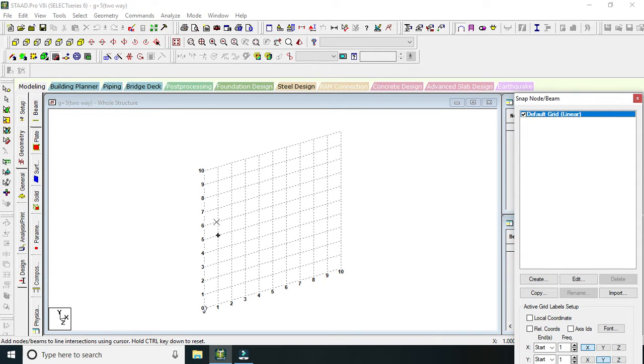So this is an X plane and this is a Y plane. Here, before selecting it, let us select the floors. From here to here let us draw this one, so that our floors will be created. Then from here to here I am going to draw the beams. After drawing the beams we will be joining them with the help of this translation tool.